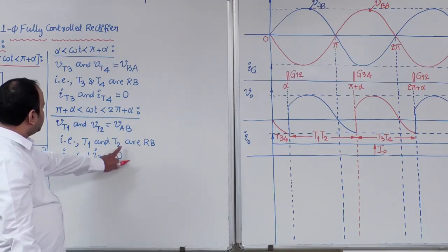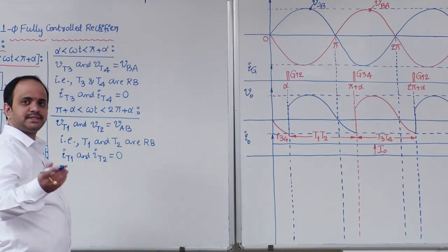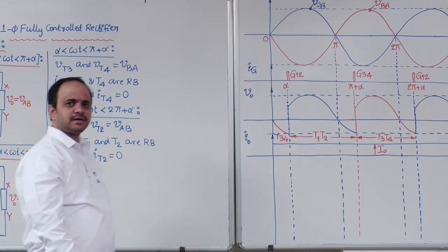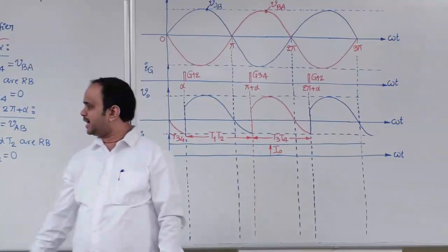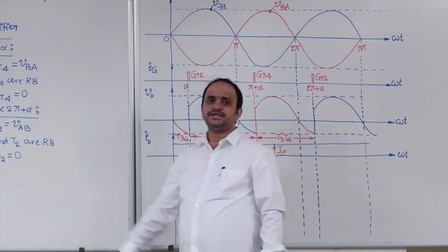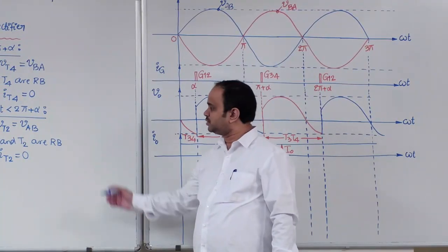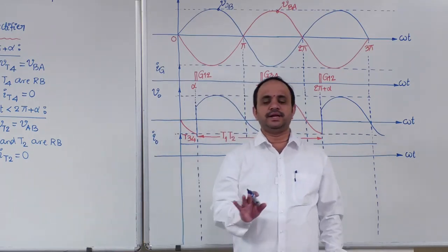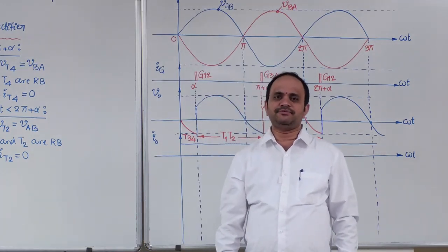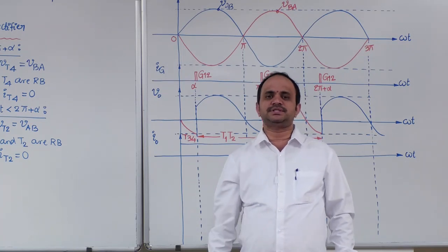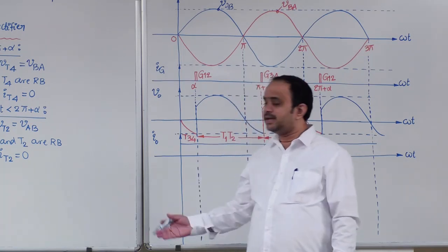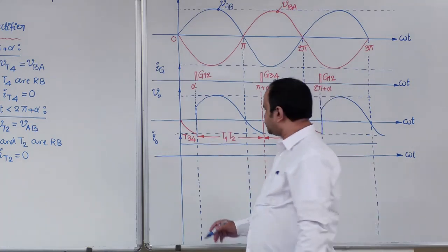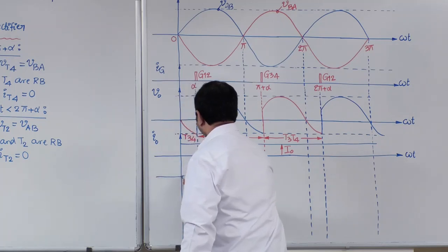Now observe carefully, these are the two basic requirements for the turn off process of a thyristor or SCR, isn't it? Therefore, we can say that the turn off conditions were satisfied with respect to the source property. There is no external circuit in order to create that. That is the reason in phase controlled rectifier circuits, the commutation process is referred to as line or natural commutation. Now, by using those conclusions, what is the next waveform?